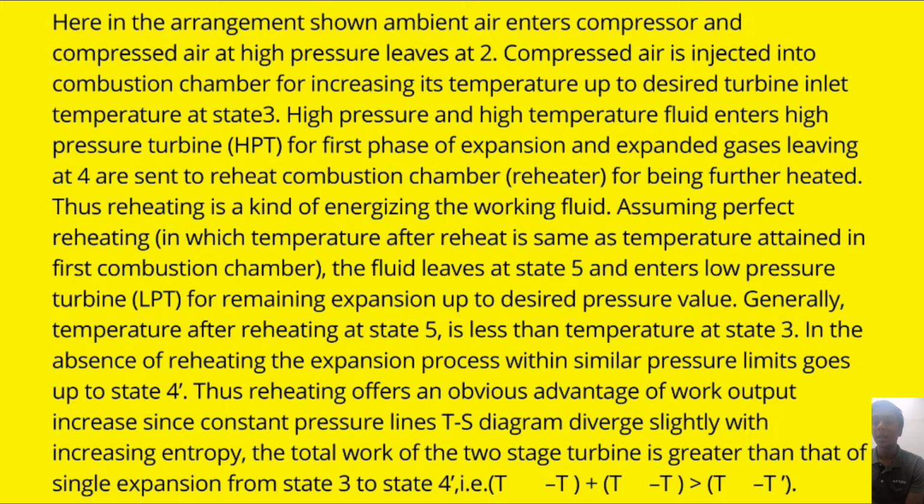Thus, reheating is a kind of energizing of the fluid, assuming perfect reheating, in which the temperature after reheat is the same as the temperature attained in the first combustion chamber. The fluid leaves at state 5 and enters the low pressure turbine, LPT, for the remaining expansion up to the desired pressure value. Generally, the temperature after reheating at state 5 is less than the temperature at state 3.